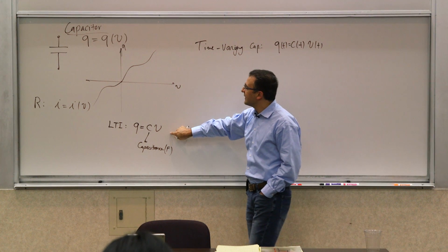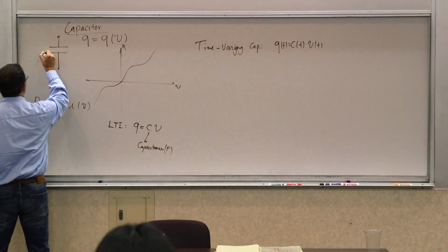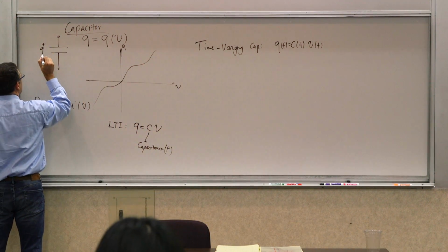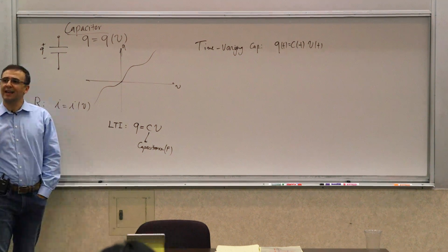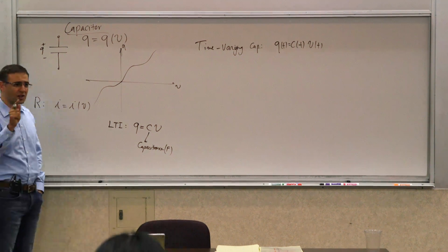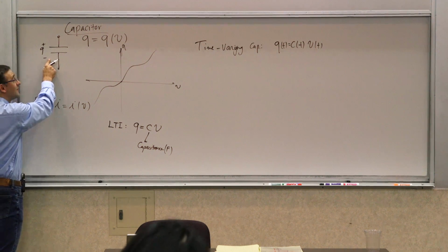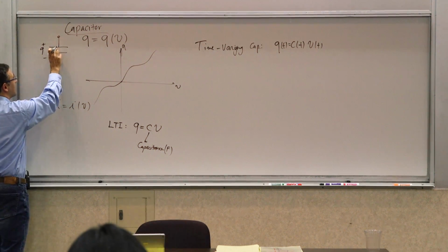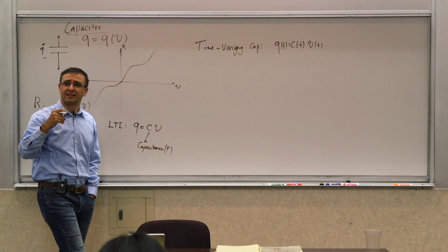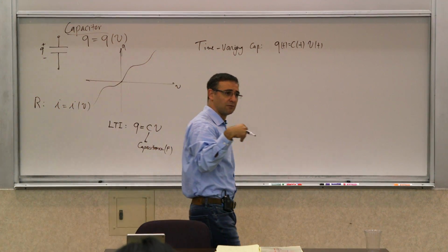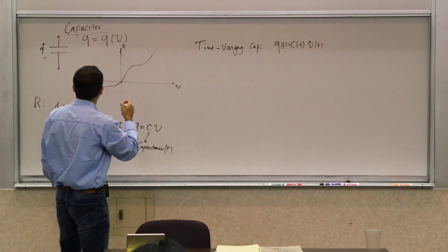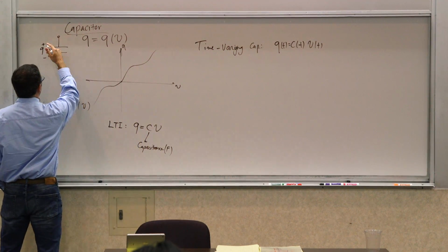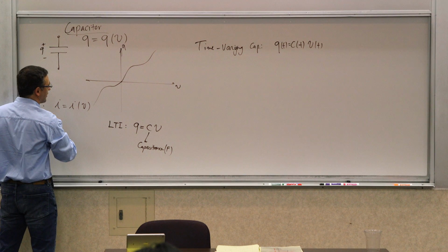So for a time invariant capacitance, if the charge in the capacitance is Q, when you say stored charge, it is correct, but you have to think about it. It's not net charge. The net charge of a capacitance is what? Zero, right? Because you get exactly the same charge here as there. And you remember from the circuit assumption and from Maxwell's equations, you don't really have charge accumulation if you're dealing with a real circuit. So what it basically says is that there's some charge distribution of this nature.